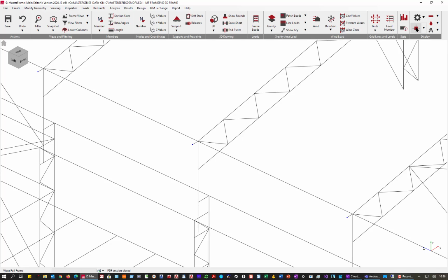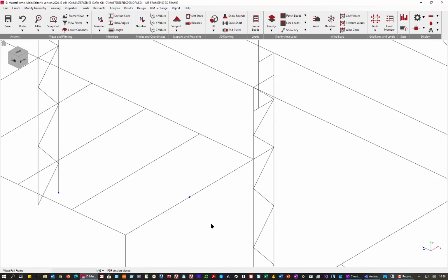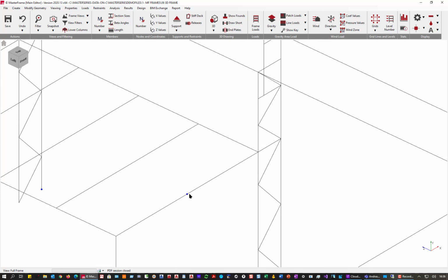And then we have the node points, so we can identify where all the node points are. Interestingly, it always draws the node points at free ends, and it would draw a node point if there was a node on a member that was there for no reason whatsoever, like this one here. It's between two halves of a member and doing nothing else, so it shouldn't really be there. But we can just merge that member and get rid of it.